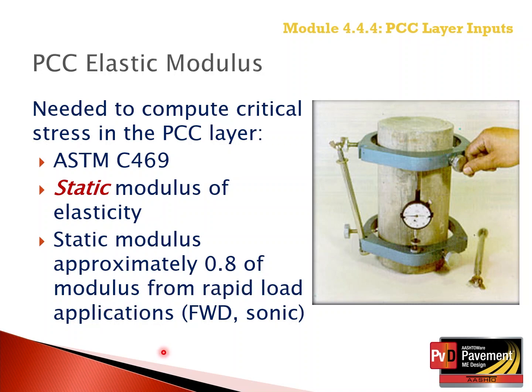A point to remember: the global calibration of the transfer function used the static modulus of elasticity from ASTM C469.